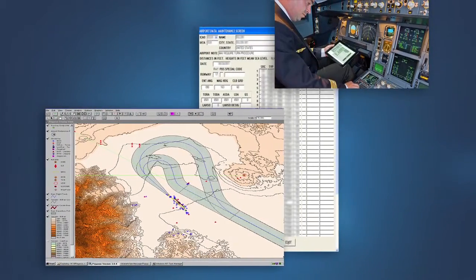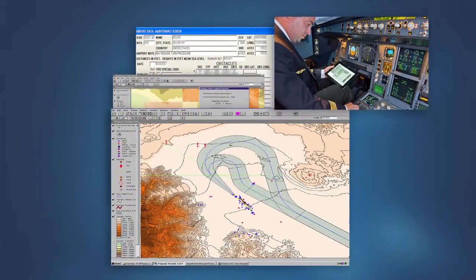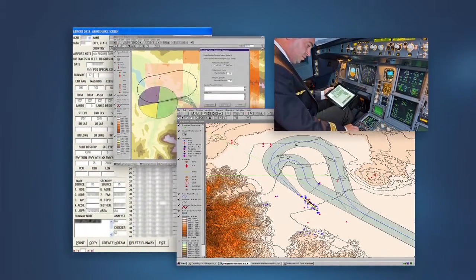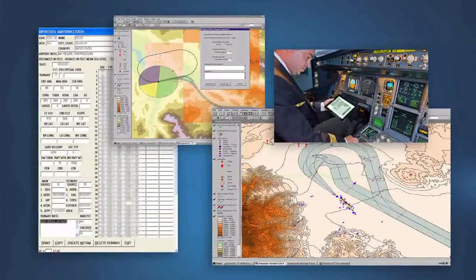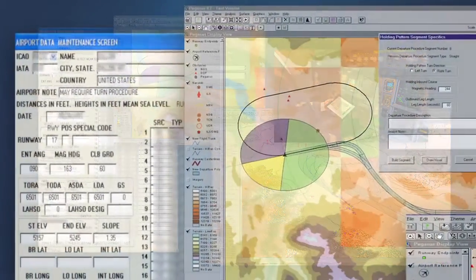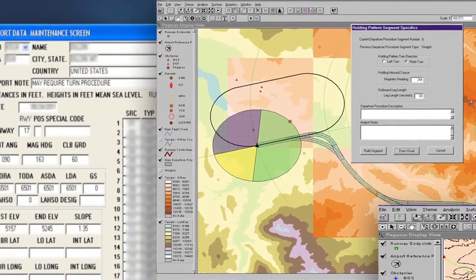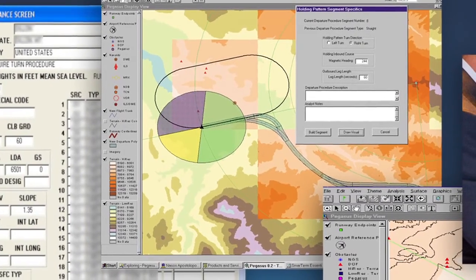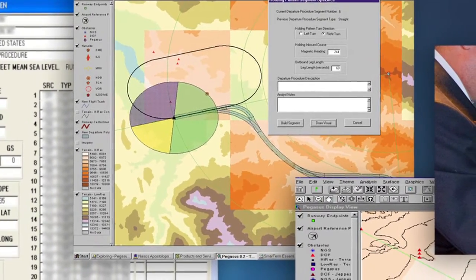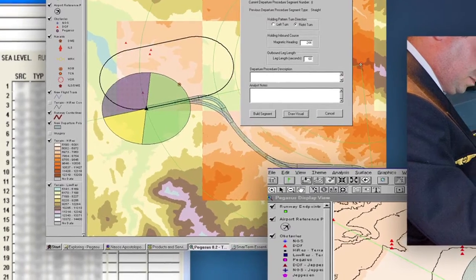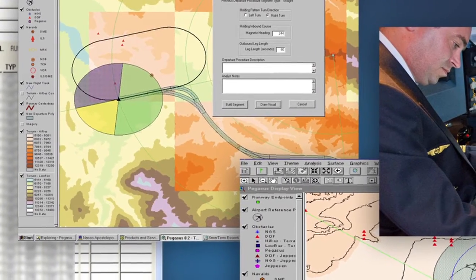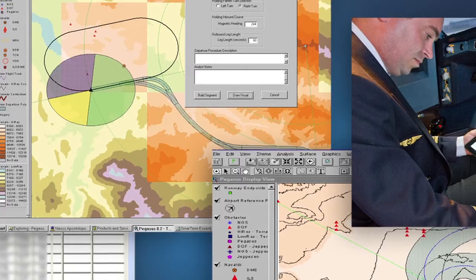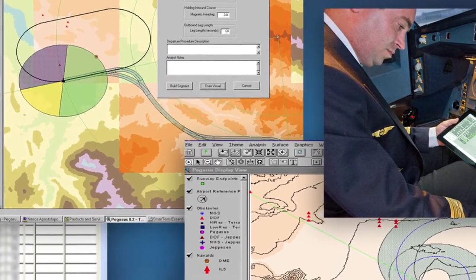Rather, it is expected that the analysis is completed by a professional aircraft performance engineer or a performance engineering provider, with the necessary training and resources available to make full use of data provided in the airplane flight manual. In addition, they are expected to collect and maintain an obstacle database using the best and most current data sources available for use in performing the analysis. In many cases, electronic performance data is now being provided by manufacturers, and in some cases the flight manual performance data is no longer provided in paper form.